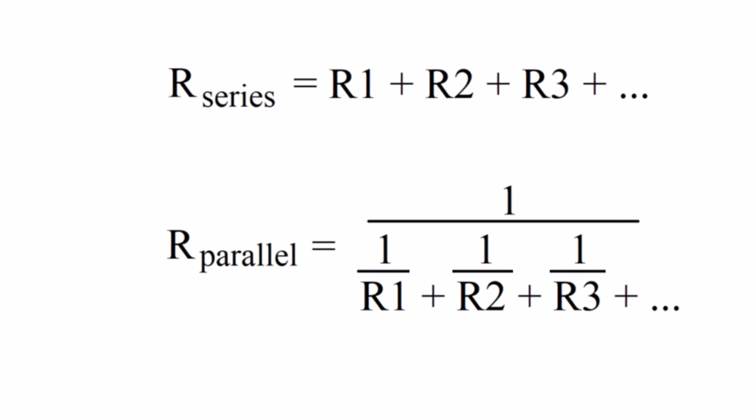smaller than the smallest value of inductors. So it's got to be less than 10 millihenries. And our answer choices are 0.3 henries. That's going to be equivalent to 300 millihenries, so that can't be right. 3.3 henries, which is way too high. 3.3 millihenries or 30 millihenries. The only answer choice that's less than 10 millihenries is the 3.3 millihenries. So that's our answer.